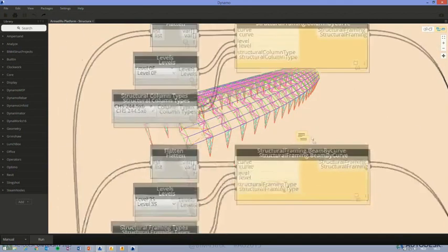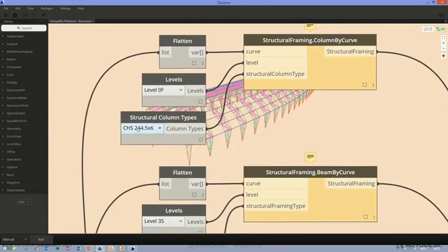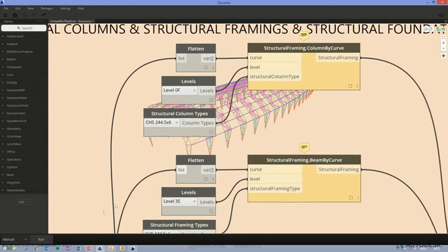You have this, and I want to make lattice structures on it, so I need to generate points again. I need to divide them on that line, and then use those points again as a basis for new lines, which will be this group of nodes. The points, here you go, and then the column bracings.